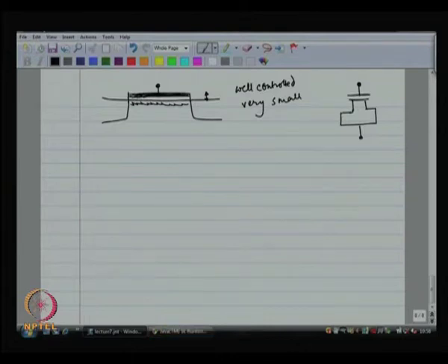This will work only when the MOSFET is in strong inversion. So, this will work when the voltage between these two nodes is more than a VT. Okay. Roughly speaking, more than a threshold voltage of the MOSFET, then the MOSFET goes into strong inversion, then there is an inversion layer of charge, basically the second plate, the bottom plate of the capacitor is created only then. Okay. And then you have a nice controlled capacitor between 2 points.